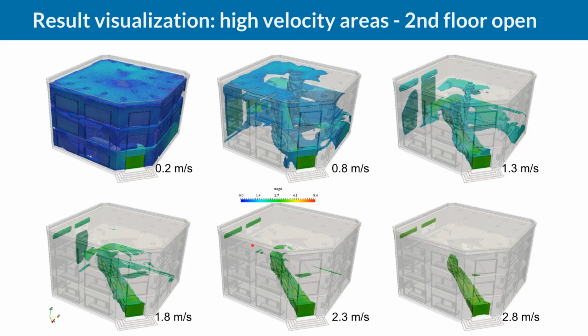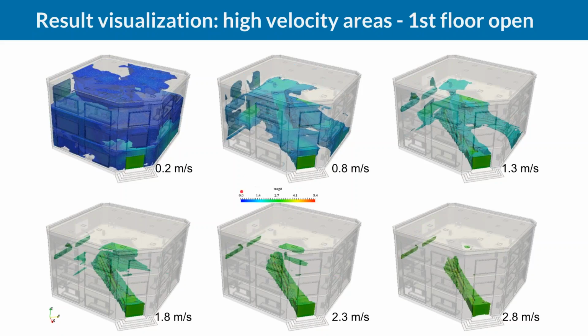The building itself is generating an external flow field. For example, behind the building you usually have a wake and a pressure drop. And therefore, the windows on this wake side, the low pressure side, will be able to help you more with natural ventilation than other windows. And we can continue this study and now take a look at a configuration where only the windows here on the first floor are opened.